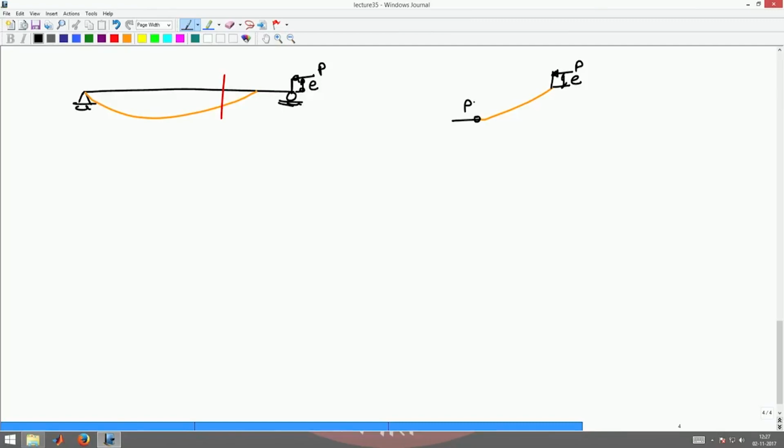I have P here. Now, again I assume that the vertical deflection is absolute value of delta y. Okay. Now, then I have a moment Mz coming in here which will be a clockwise moment to counter the anti-clockwise moment produced by the axial force. Okay. So, now the Mz moment is given by P into (e plus absolute value of delta y).